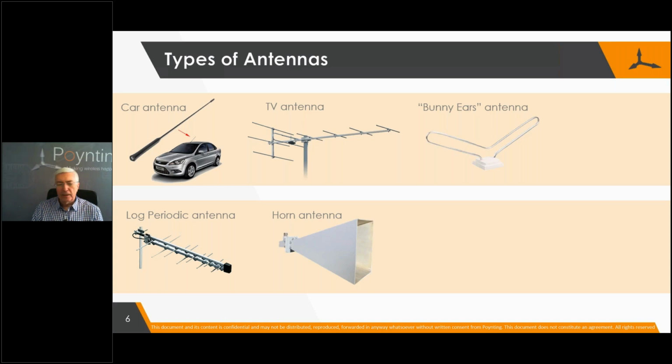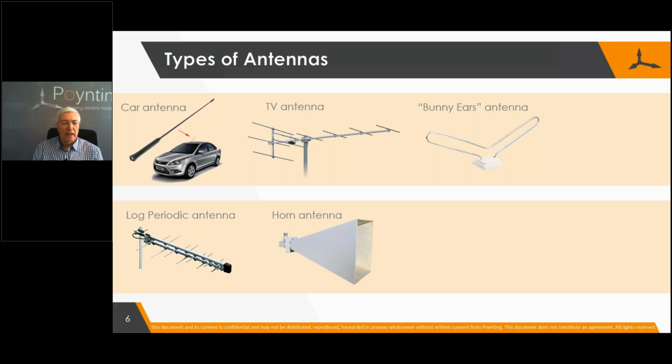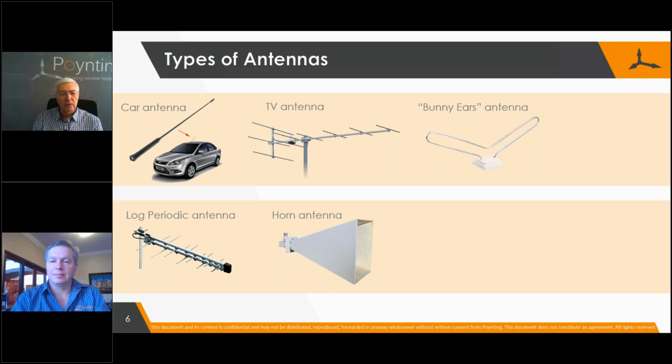Then this is a funny looking antenna. This is a horn antenna. I've actually designed some of these when I needed to do spectrum analysis on towers, and they typically have a fairly narrow band and a fairly high gain. Again, obviously meaning the ability of the antenna to gain a signal. Stephen, I see you wanting to jump in.